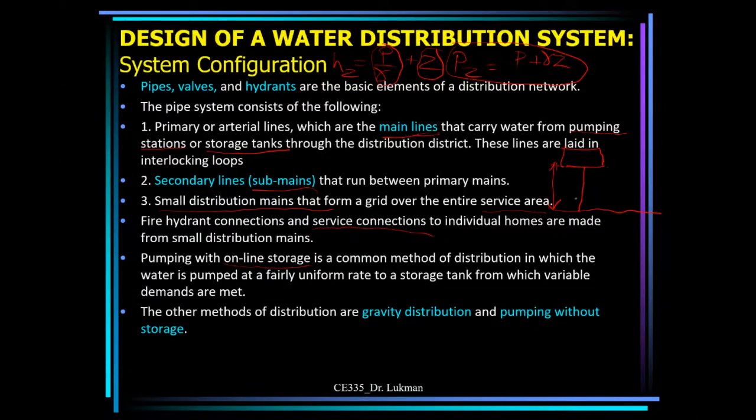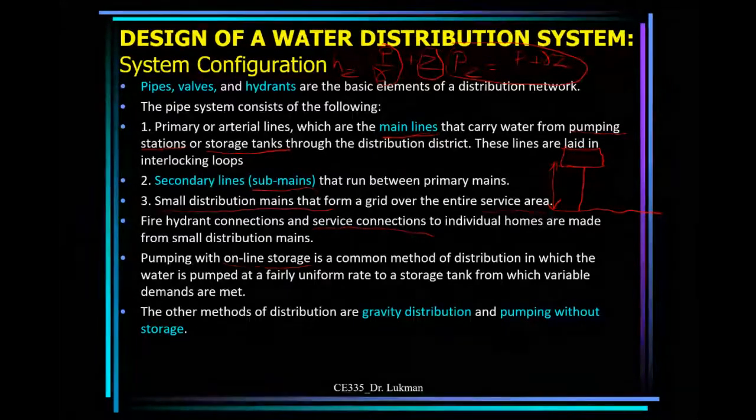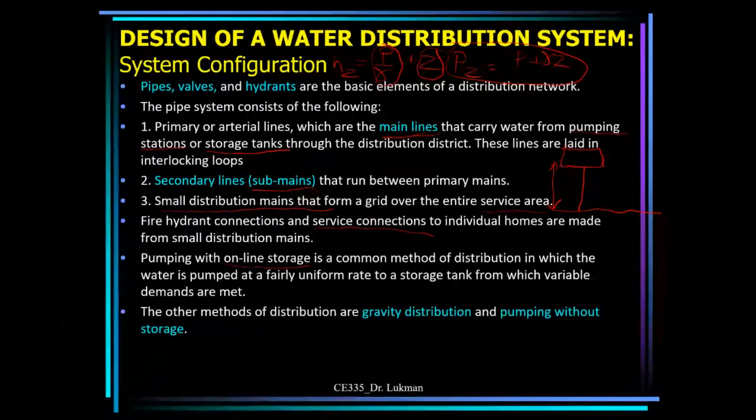So it is raised above ground level. The elevation head is more or less in the form of the potential energy possessed by the liquid, which will translate into the piezometric head, which will add to the pressure head of the liquid. This is the pressure head. When it is raised above the ground surface, the piezometric head increases. That means the pressure head will rise to somewhere here, depending on losses. So this flows by gravity into the mains, into the distribution network.